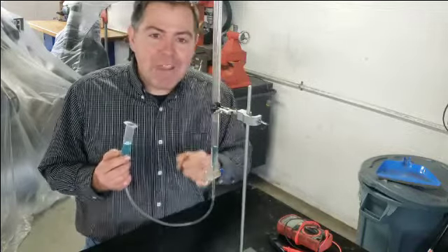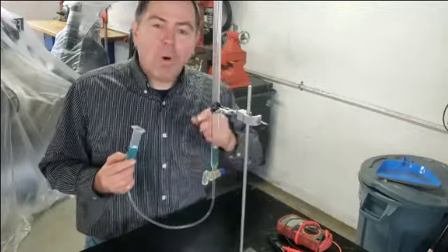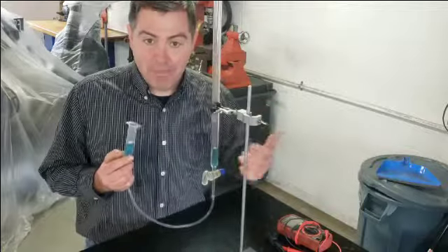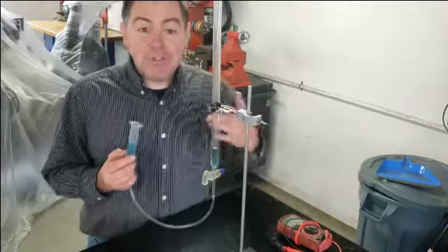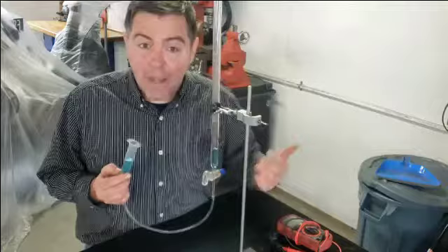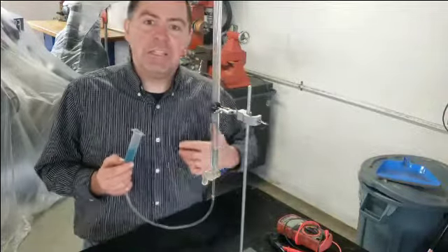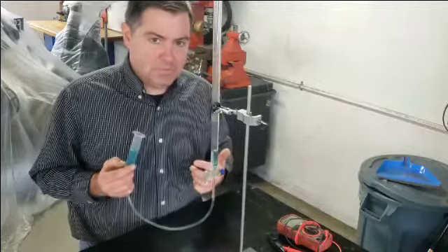If we didn't have counter electromotive force, what would happen is we would have an excessive flow of current to that fan motor. Eventually, what would happen is our wiring would heat up, our resistance would become higher due to the hot wiring, and we would actually see a decrease in speed of that fan motor.